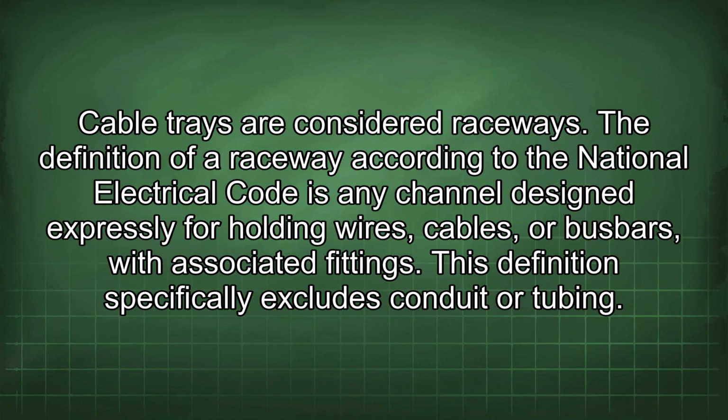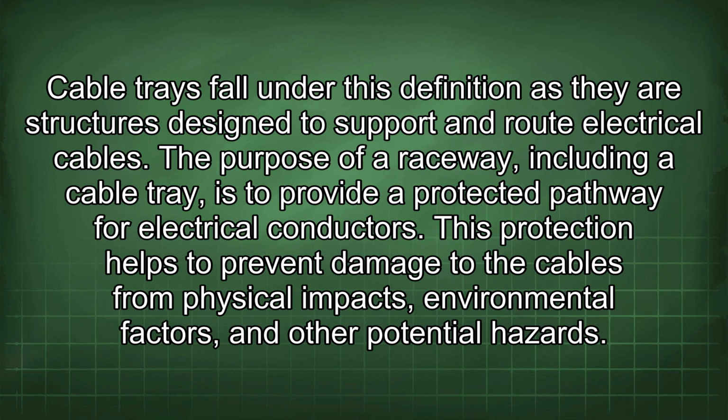Cable trays are considered raceways. The definition of a raceway according to the National Electrical Code is any channel designed expressly for holding wires, cables, or busbars with associated fittings. This definition specifically excludes conduit or tubing. Cable trays fall under this definition as they are structures designed to support and route electrical cables.